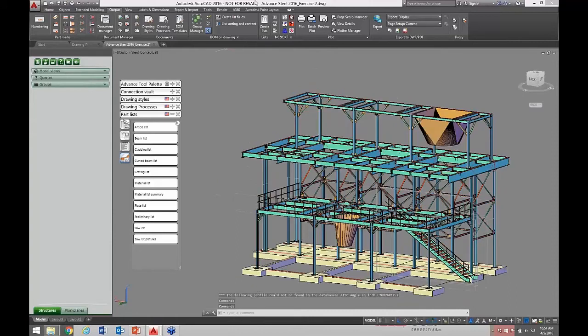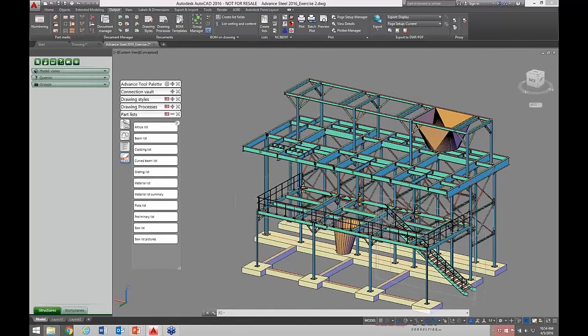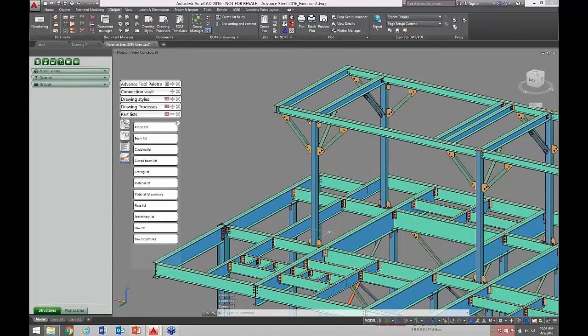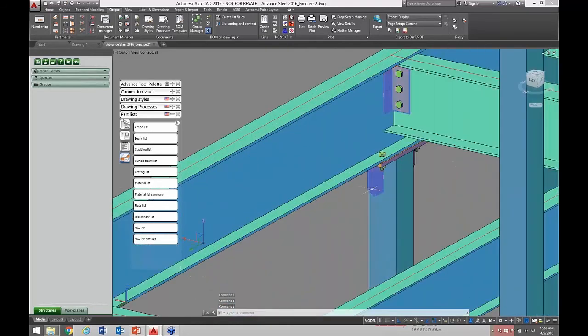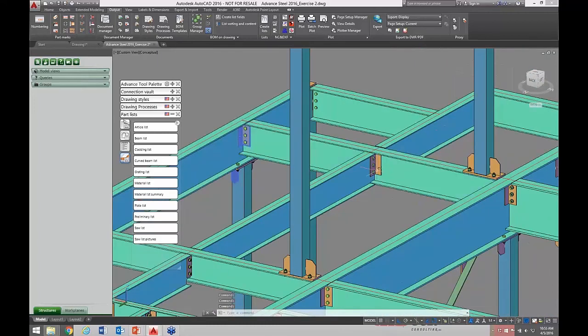All right. We have the ability to actually do NC data, DXF export. We could DXF all of our shapes, or we could DXF plates, a particular command that I'm going to use for you. But let's not pick all plates. There are a large number of connections in here. I could filter, but let me just pick a few items here. That should be enough for us.